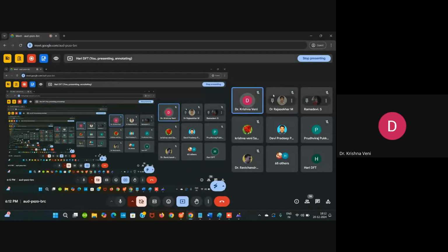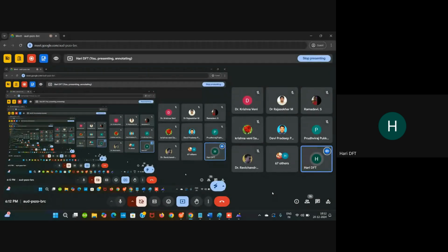Okay, let me explain. It is a case of neither nor, because the entire RTL to GDS flow is mandatory for chip design, but most people don't know that without DFT we can still tape out the design. DFT is only mandatory when we go to mass production. Please remember this word, mass production. When an organization or any MNC goes for mass production, then and only then does DFT come into action.